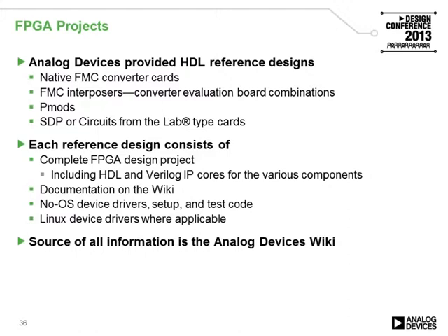Analog Devices provides HDL reference designs for native FMC converter cards, converter evaluation boards using the previously discussed FMC interposers, Pmods, SDP or circuit from the lab type cards. Each reference design consists of a complete FPGA design project, including HDL and Verilog IP cores for the various components.